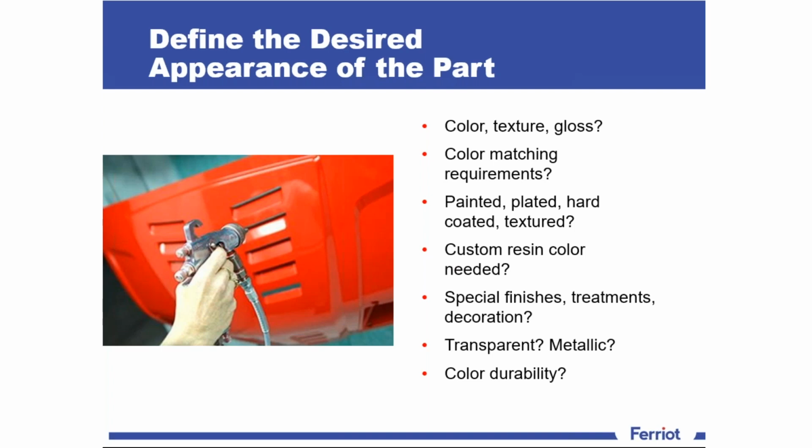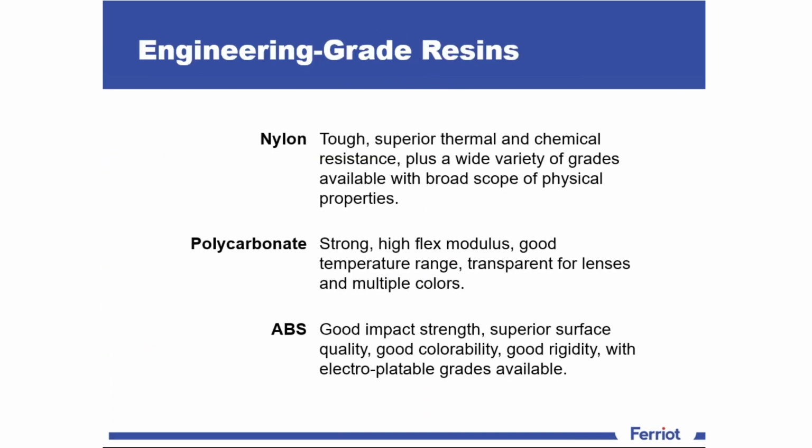If the part must maintain a specific color over its lifespan to match the color of other parts in a final assembly, the resin selected must be resilient enough to weather and wear at the same speed as the other materials without yellowing or otherwise discoloring. Start now to narrow down the possible resin types for your part.